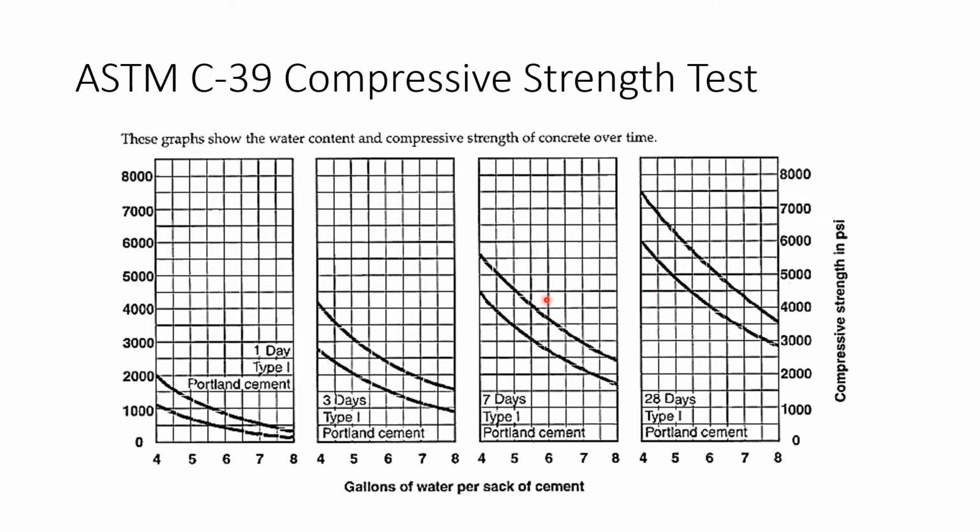And you can see how the graph goes up, yeah, compressive strength goes up as you have more and more days, so 1, 3, 7, and 28 days, yeah. The same type, by the way.